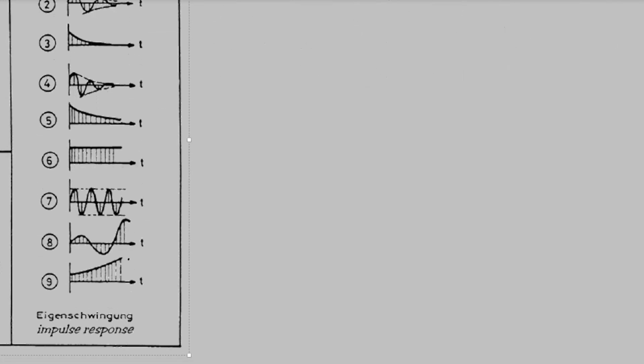If I shift this a little bit higher, then we have the same situation if my impulse response causes an oscillation with constant amplitude. Again, this is the border case between stability and instability. We cannot say this is stable, but we can also not say this is unstable. Instability is very clear. It is when the amplitude of an oscillation is increasing to infinitely large values, or if the exponential impulse causes an increase which is never ending and you lose control. Now, these are some examples of systems. The upper cases are stability, the lower cases are instability, and there are some intermediate cases.